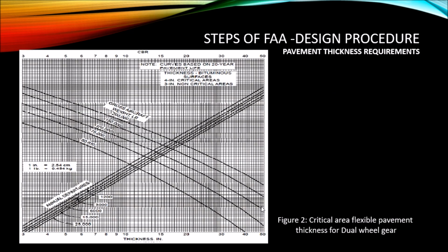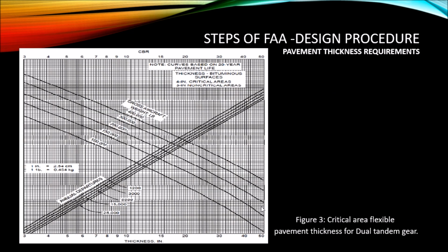700,000, dual T. So this is a dual T graph, as you can see. Here, 1,200 annual departure, and then it has the one of 700. You can see the maximum that we have here is 400. So we can use 400 for any weight that is above that. So here we move down from 10 to where we have the graph of 400.